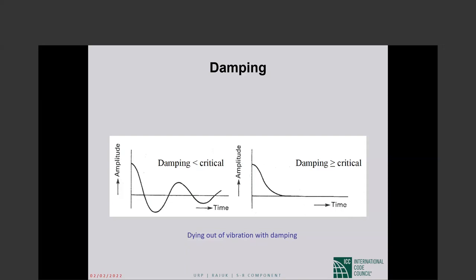The pendulum eventually comes back to rest. It does the same thing as the building. The back and forth motion, the amplitude decreases with every move, and eventually it comes back to rest. In the case of the pendulum, the damping is produced by friction with the air. In a building, damping is produced by the damage that is sustained in the process of going through an earthquake.